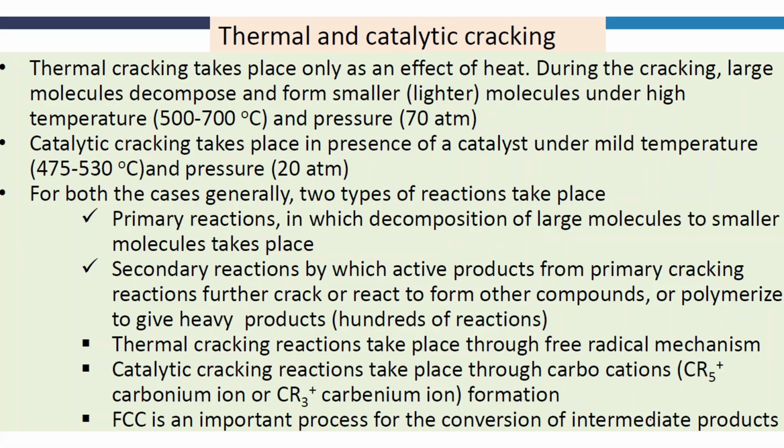The first one is thermal and catalytic cracking. Cracking, as the word itself says, is the cracking of heavy hydrocarbons to lighter hydrocarbons. And it is done in two ways. The first one is thermal cracking, and the second one is catalytic cracking. Thermal cracking takes place in the presence of heat, whereas catalytic cracking takes place in the presence of catalyst. During cracking, large molecules decompose and form smaller molecules under high temperature.